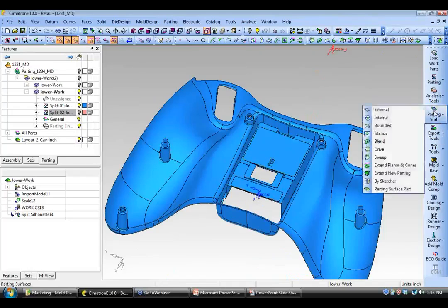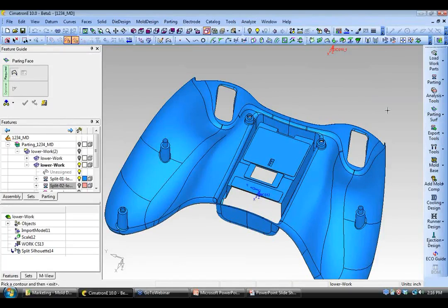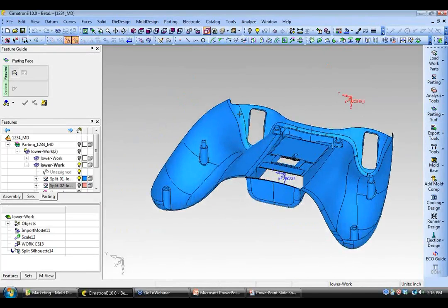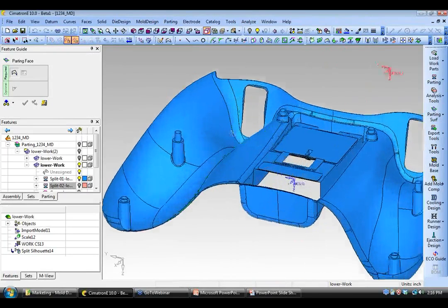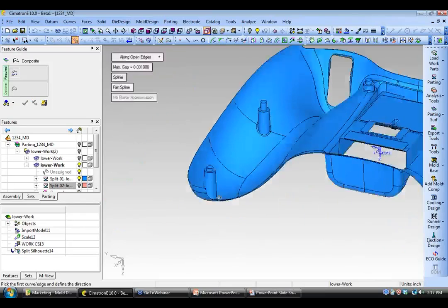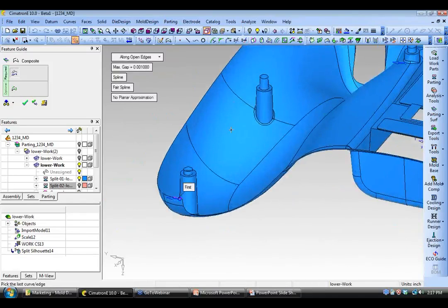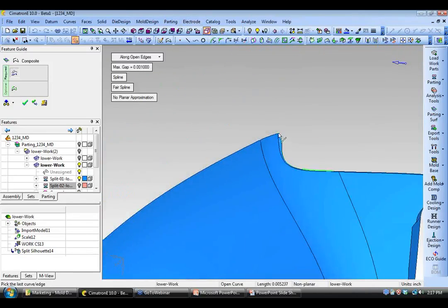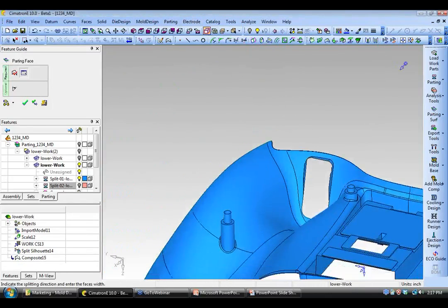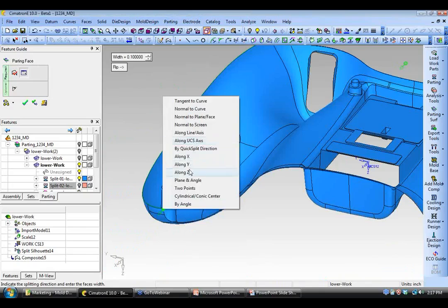And the first one we're going to use is called external. It's really ideal for parting lines because it spreads out from the part edges, but it stays as flat as possible to the draw direction. So in the beginning here, I'm going to change some edges. And then I need to fix the vector direction. 0 indicates draw.